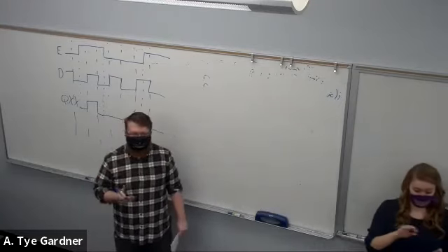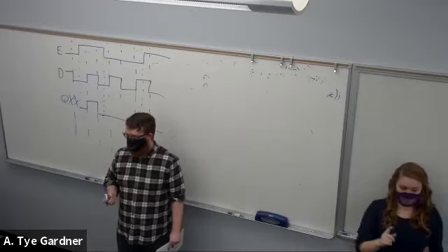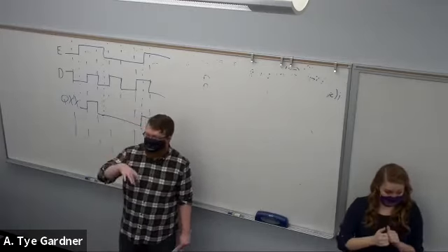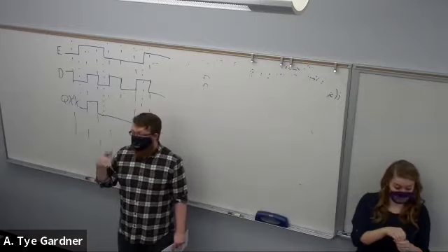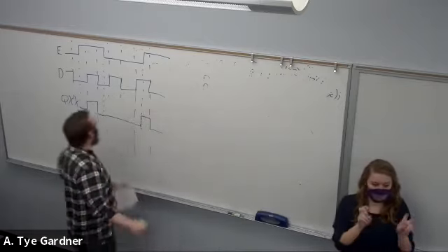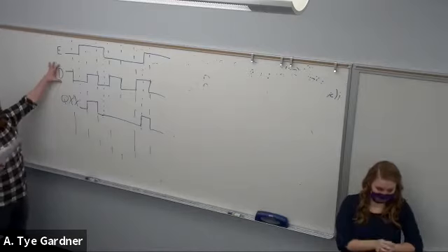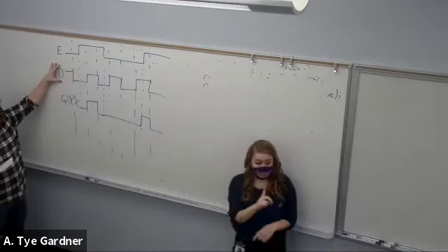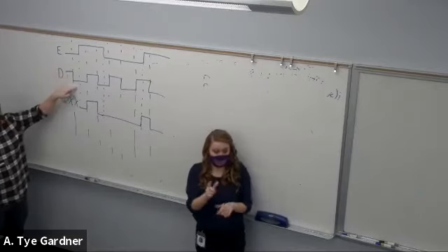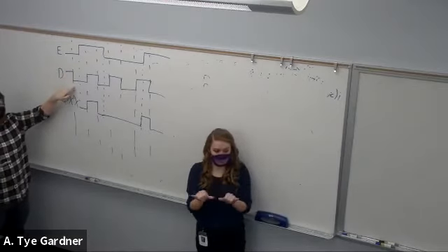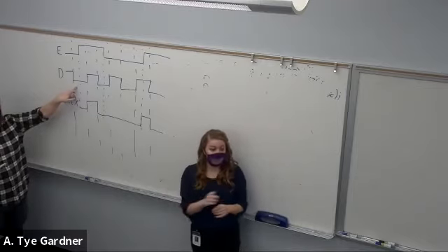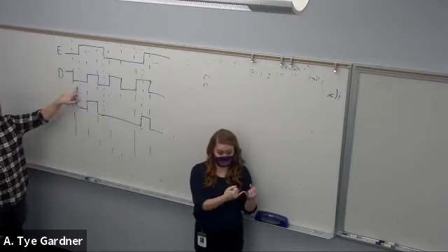And it's different in that it is clocked, meaning it only updates the input to the output on an edge of a clock. So here is basically what a clock would look like, meaning at regular intervals, it changes from high to low. This is what your digital circuits know as time. They don't know anything other than a clock is time.